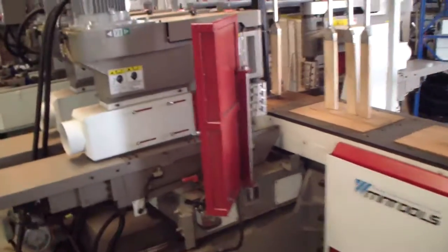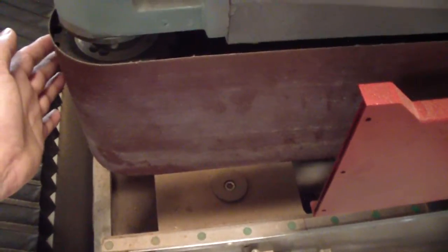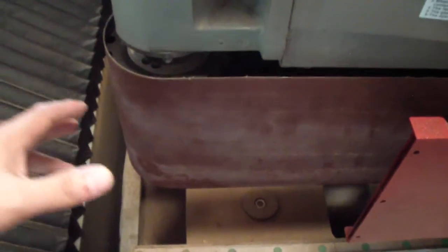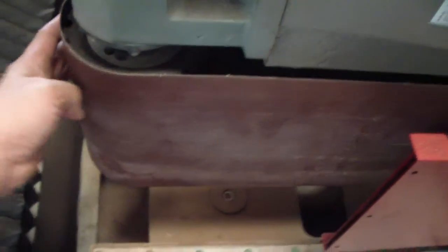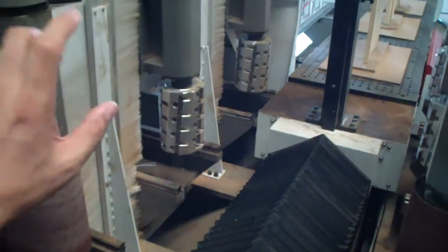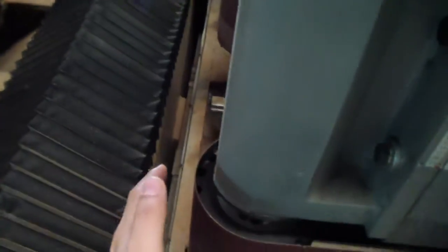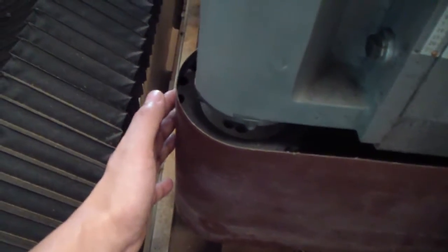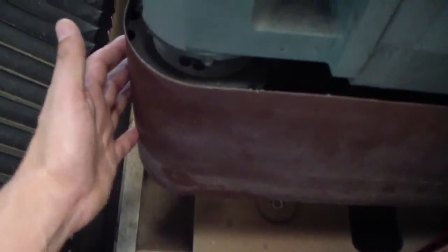Now we will introduce how to do the calibration for the sanding belt. When we do this one, it will be a little complicated. We cannot use a sanding belt to do the calibration. We have to use a hard cutter. We need to change the spiral cutter onto this spindle and do the first calibration like the first cutter. After it is corrected and calibrated and all sizes are okay, we can change back the sanding roller and sanding belt.